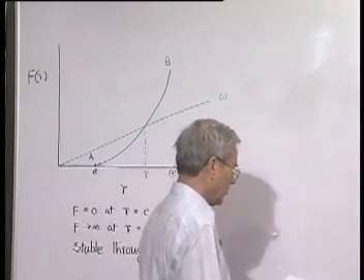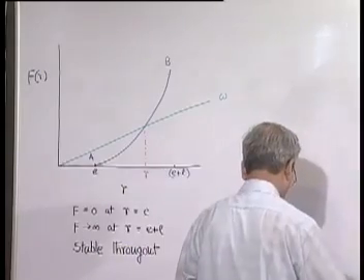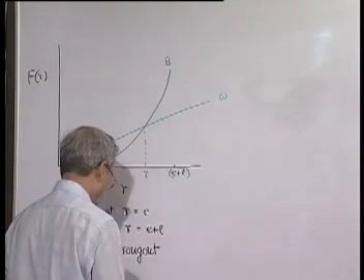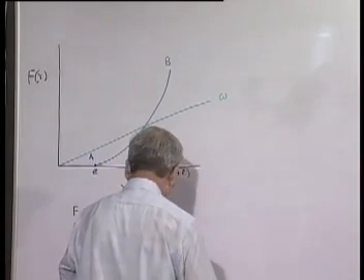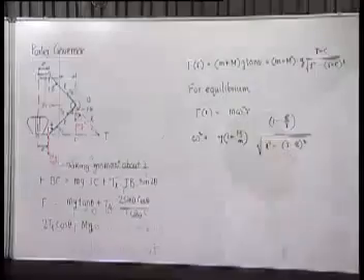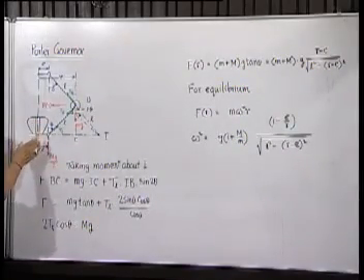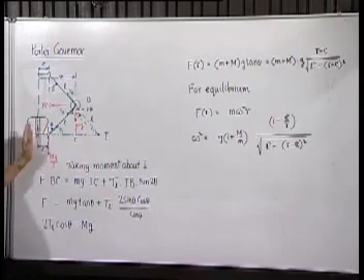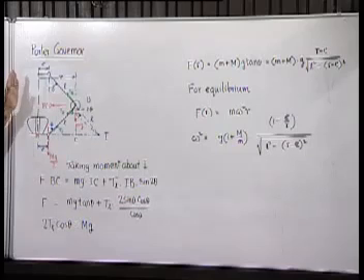Only one thing we can discuss here quickly, that this derivation is fine. Only one thing we have not been able to take up, and let us take up that. We have not considered, that means when the sleeve moves, we have assumed a perfectly smooth situation with no friction. But in reality, it is not the case. There will always be a certain amount of sliding friction involved, because it is a sliding motion of the sleeve and the central weight along the central rod, which is the central axis of the governor.